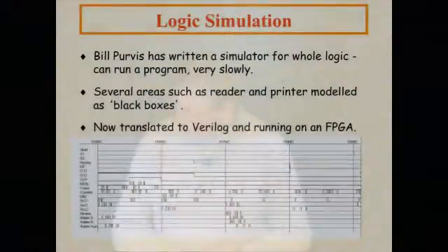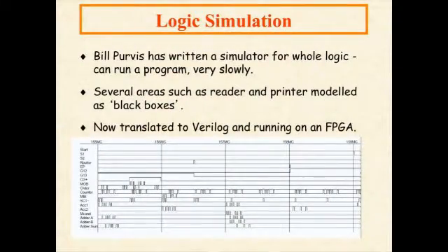I think my slides got out of order. What our logic simulator gives us is these kinds of pictures that show us how the machine is clocked, what signals are turning up where, and at what time in the machine. This simulator can run programs, so we're fairly confident it's EDSAC. Obviously, it's a simulator. On the real machine, our pulses don't have nice clean edges like that. There are all kinds of delays and echoes and so forth.